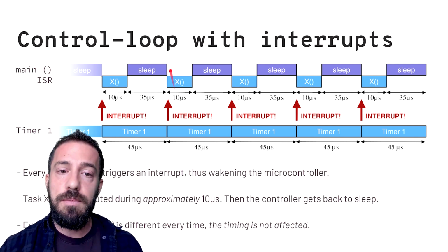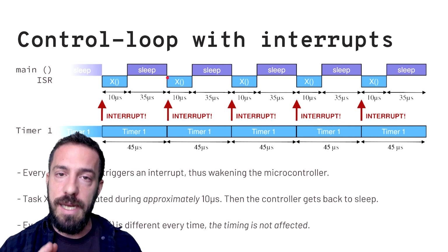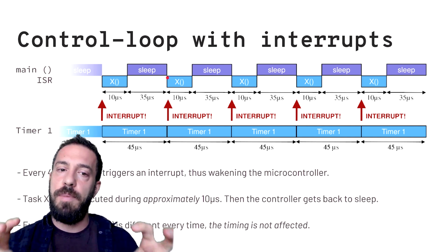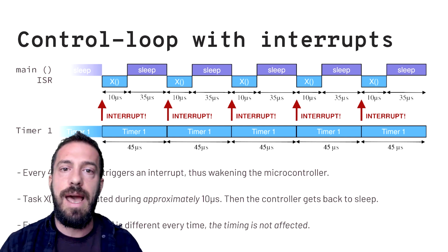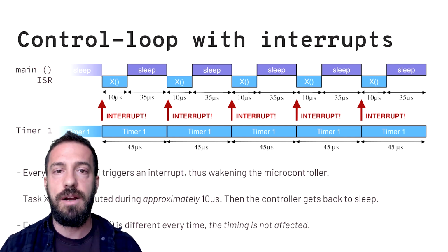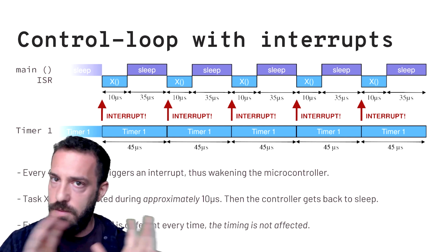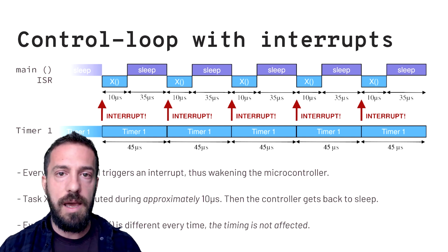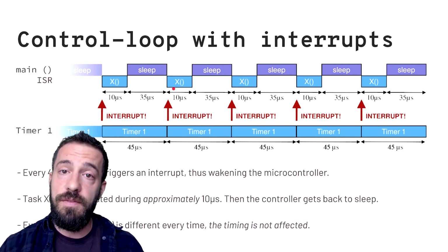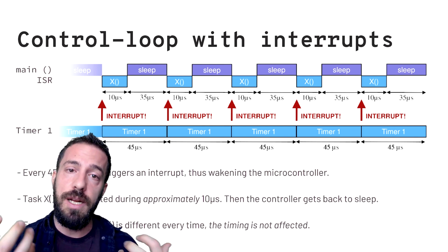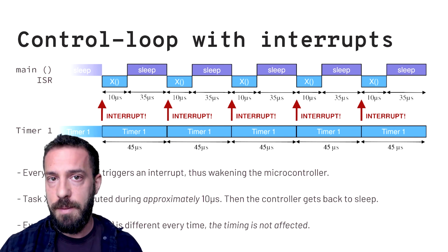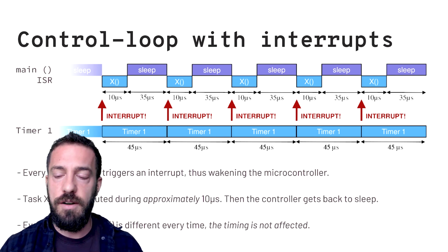So here I have much more precise timing in when I'm reading because I've calculated an upper bound, and I talk to my control engineer and they say, you have to be scanning the inputs every 45 microseconds. And if you fall within that, you're fine. You can do 10, 9, 17, it's fine. So this is the alternative to the super loop. That timing guarantee is there, but then you need hardware support and you need interrupts to be properly set up to support this kind of a scheme.